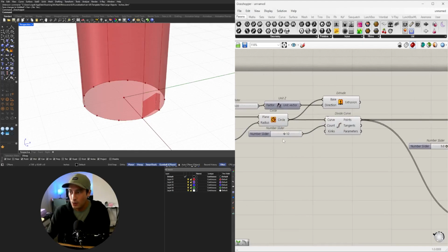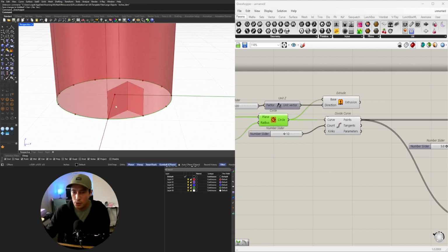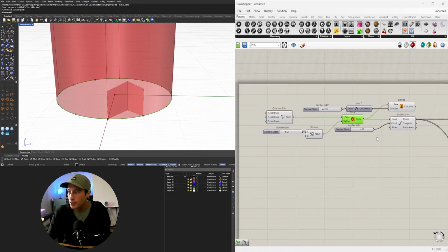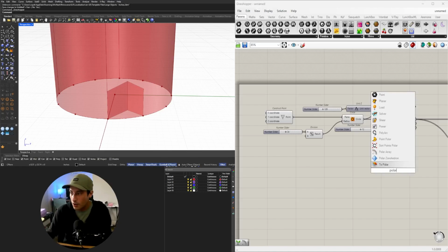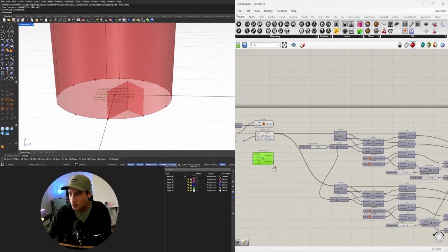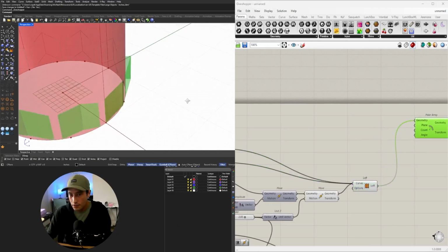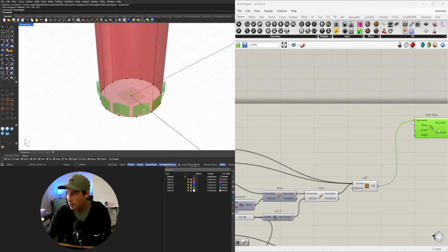And now we can do a calculation to be able to array this. Now there are two ways to array this, one using polar array and the other one using series. I typically use series, but in this case I'm going to use polar array, which lets you plug in a geometry. What's the geometry? The loft. Where is it going to be arrayed at?